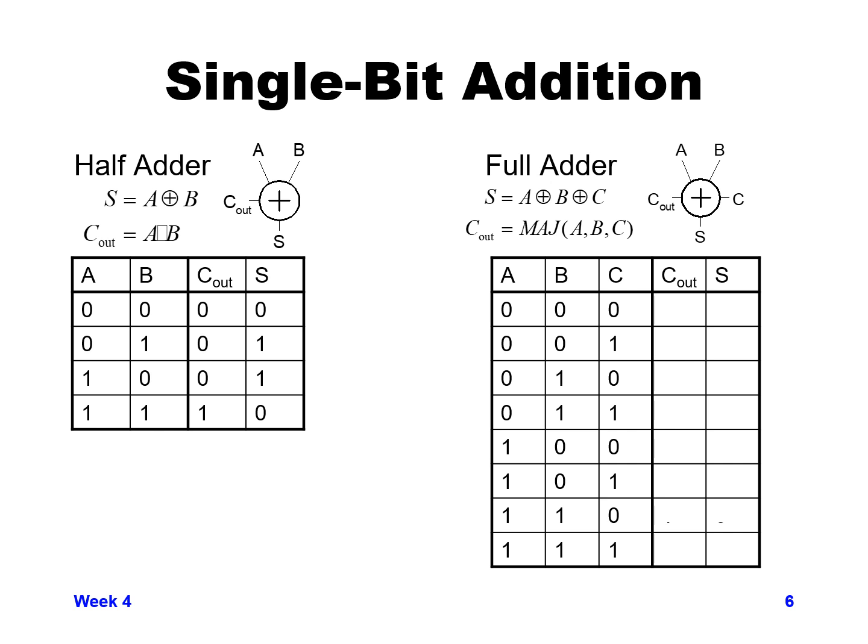In this particular case, our sum is now going to be an XOR. The XOR function is if 2 inputs like A and B are both 0 or both 1, you get a 0 out. But if either one of them, but not both, is a 1, you get a 1 out. So you get a 1 if only one of them is a 1.